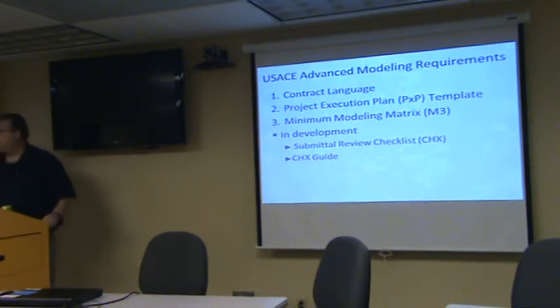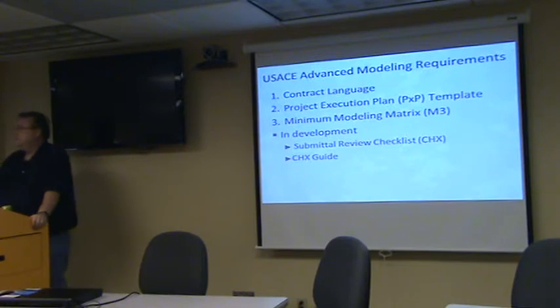How do you handle the LOD on existing structures? Because the LOD is very heavy on the I in BIM. There's a reason why. For new construction, it makes a lot of sense. For existing, it can be pretty tough because you've got to go out and verify all kinds of things to meet the I part of the BIM in the LOD. Do they require that for existing buildings, if it's in the contract? Yes. Because the goal for the Corps in general is they want a facility database.